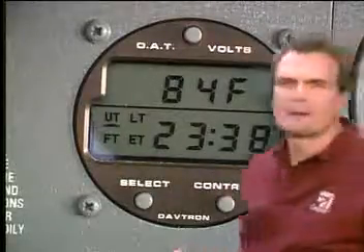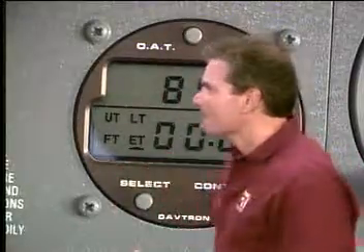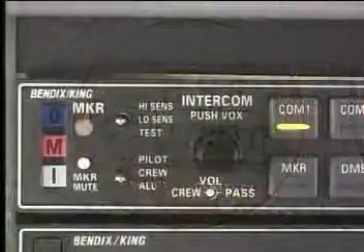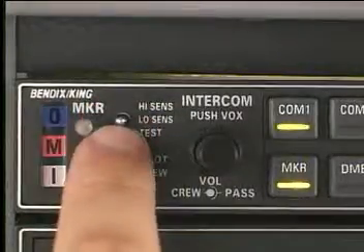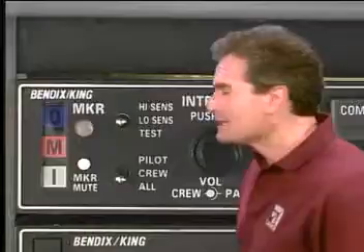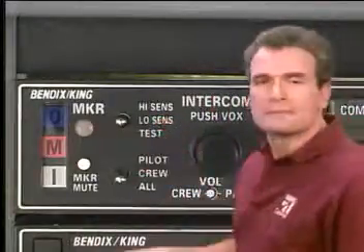Next, set your timer up so you can start the time as you cross Ellis. That way, if you end up flying the approach in a localizer-only mode, you'll be all set for determining the missed approach point using time. Now move up to the audio panel. Select the marker beacon audio and test the lights. Then set the sensitivity to low for the approach. By setting the sensitivity to low, you reduce the area where you can pick up the marker beacon signal, and that gives you a more accurate position fix on the localizer.